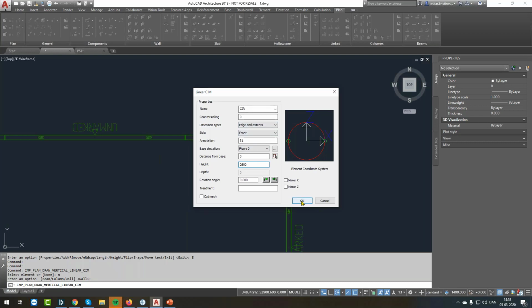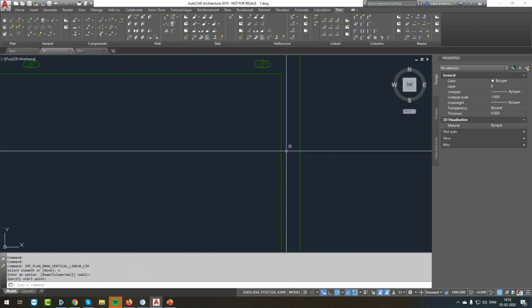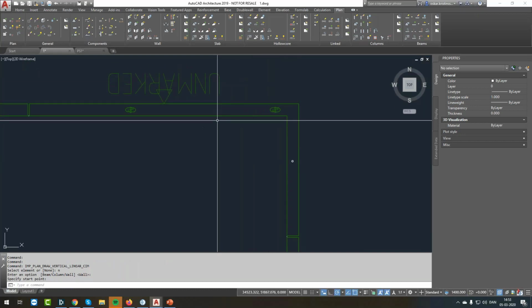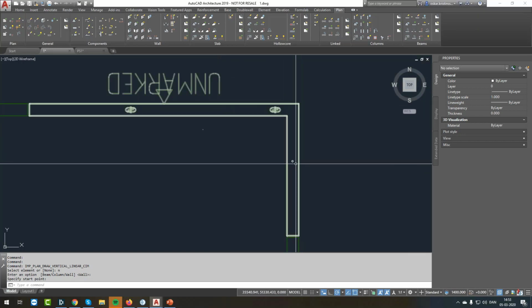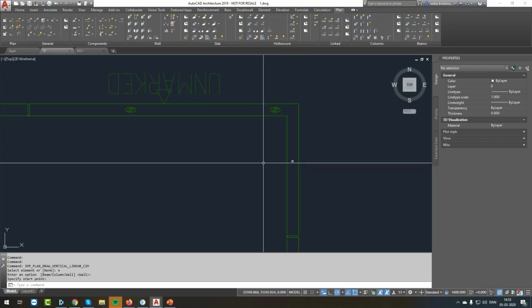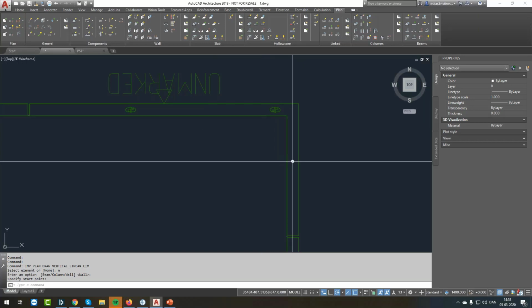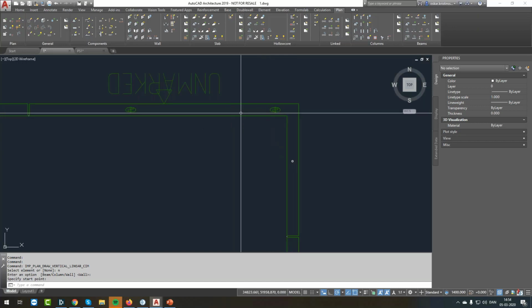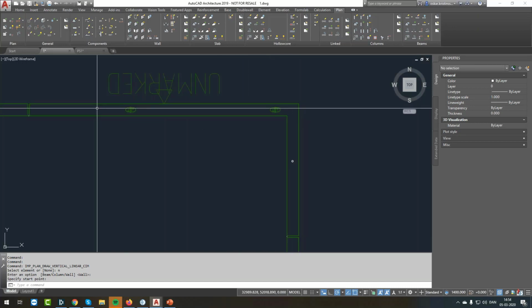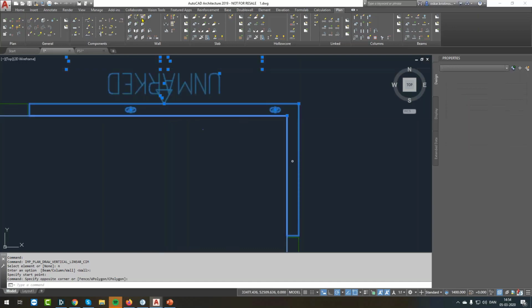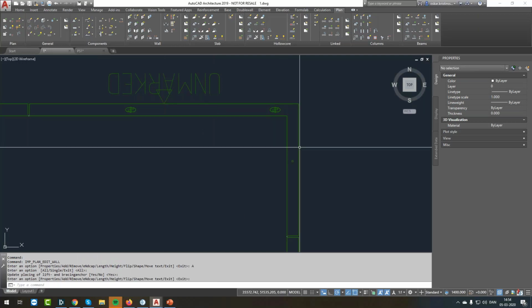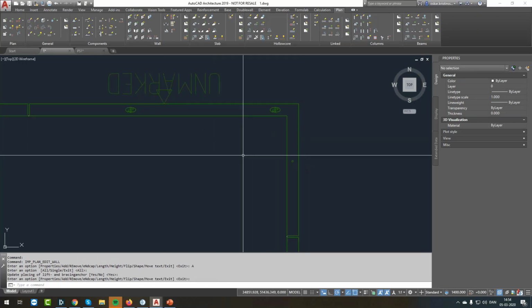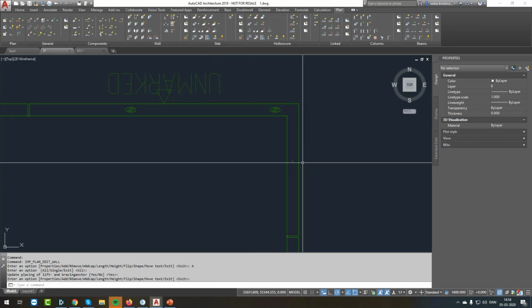We have it like this, and then when I click it here, before, in the older versions of Impact, if I tried to add this linear custom material in this end cap here, it was not possible. It would just get rejected, because the insertion point of this linear custom material was outside the main geometry, which is the thickness of the wall. But now it's possible to add this one in here in the element, and it will not get removed if you update or something like that.